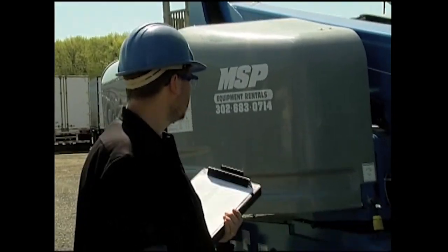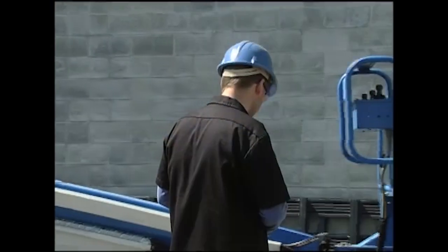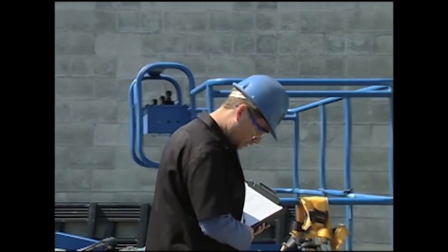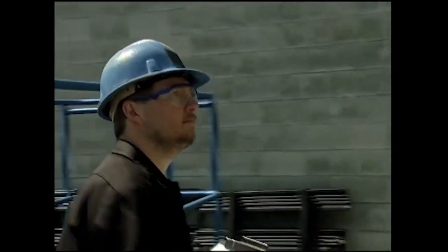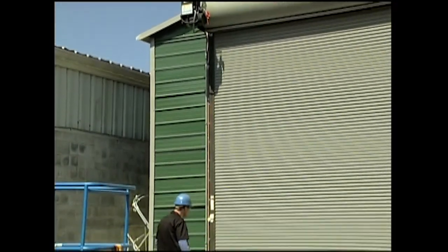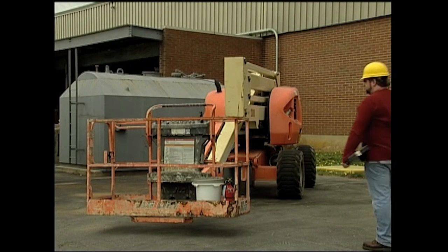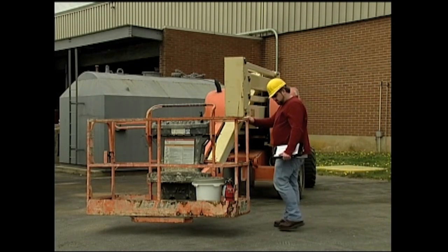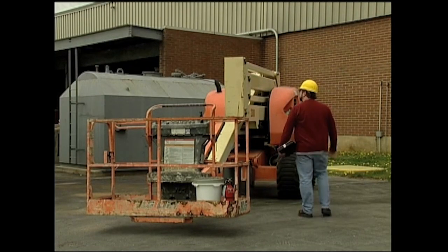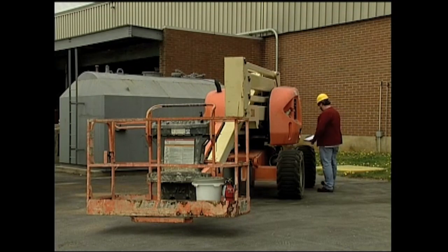Before you use an aerial lift, you want to make sure it's in good working order and there aren't any problems with the area where you'll be set up. There are two different inspections that must be performed before using a lift: the pre-start inspection and the worksite inspection. You should inspect your lift prior to the start of every work shift. This will ensure that nothing's happened to it while you've been away and that it's still in good working condition.